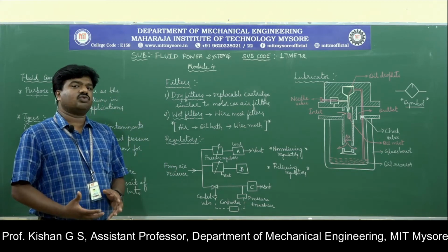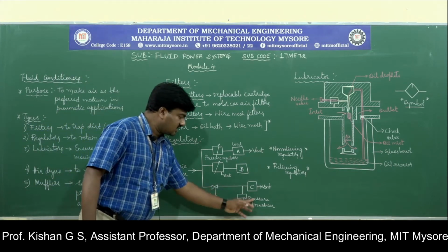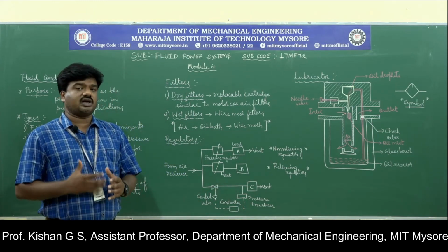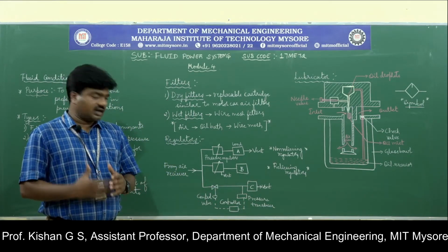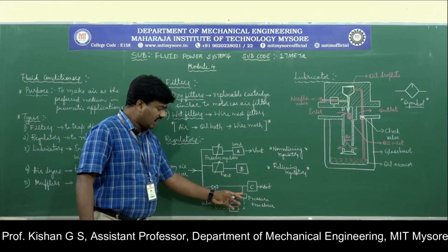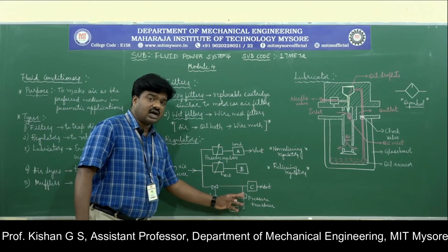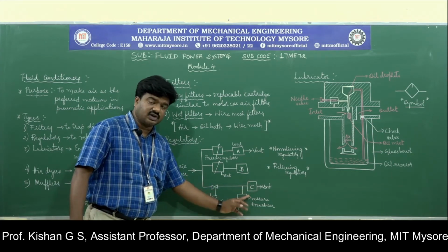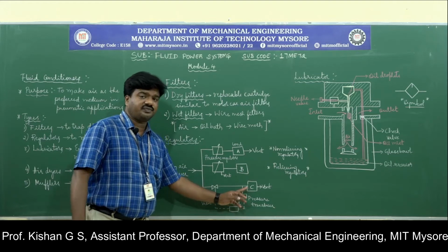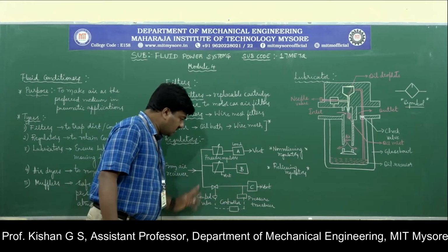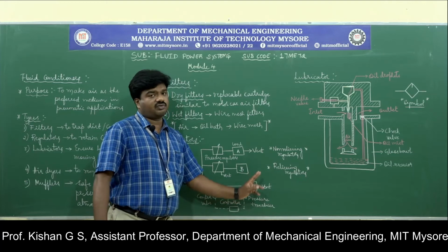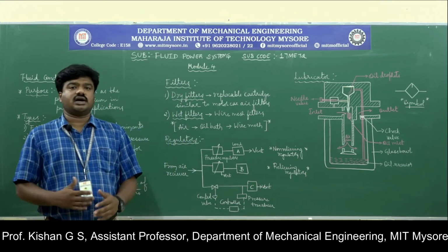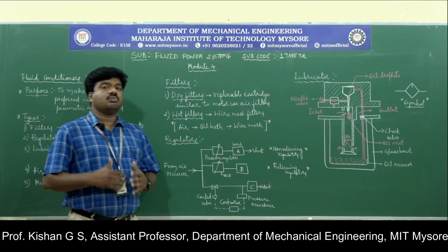At that particular time, if the pressure transducer identifies that the pressure at which the air is being taken into the system matches the necessary amount of pressure required to perform the work through the load C, then it feeds the air from the receiver to the load C to perform work, and at the end there will be a release of pressurized gas into the atmosphere. What happens if it is more?